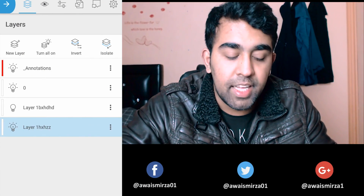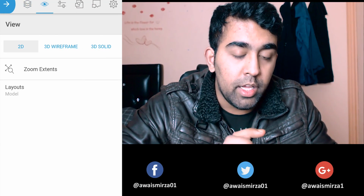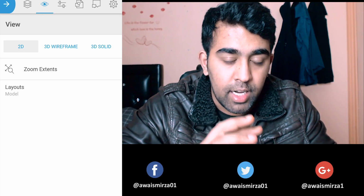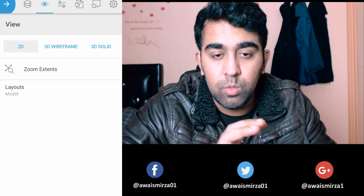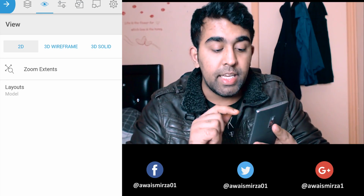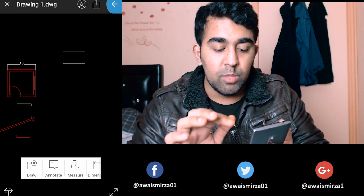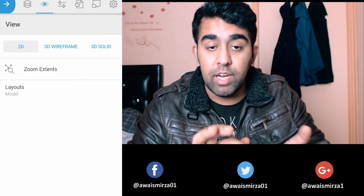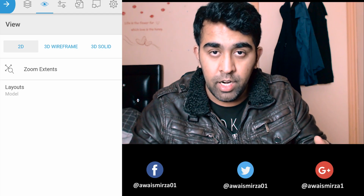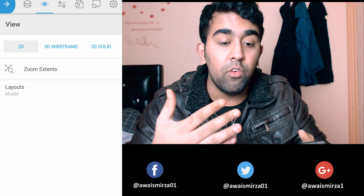Let's jump to the next setting, right? So we got some view option here. So if you are lost in your drawing and you want to zoom, extend, whatever comes in your drawing, what are the objects available in your drawing, you can directly access them by tapping here, zoom, extend. It's going to zoom, extend to every object. Alright, so let's go back to setting now. You got 3D wireframe. If you import a 3D object from your AutoCAD software, you can basically import that and look at it in the 3D view, which is really cool, right?